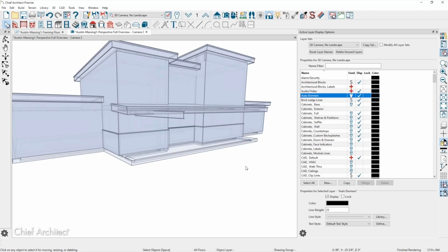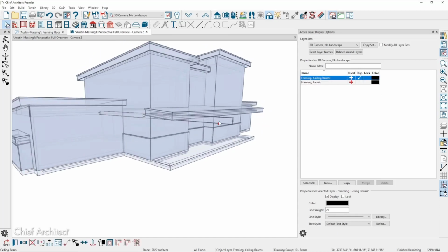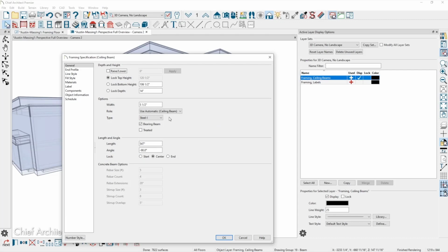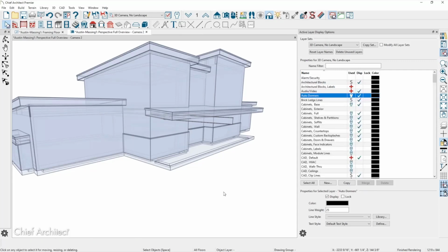Yeah. Now it looks like that is perhaps an I-beam, a steel beam. Yeah, my default beam probably was an I-beam. So if you look at this as a steel I, okay, there it is. In your default settings, you can set your beam type. When I've been doing some of the recent designs with the work, I've been using more steel posts and steel I-beams. So I've set my default to be that style. And you can find that in your default settings under framing.